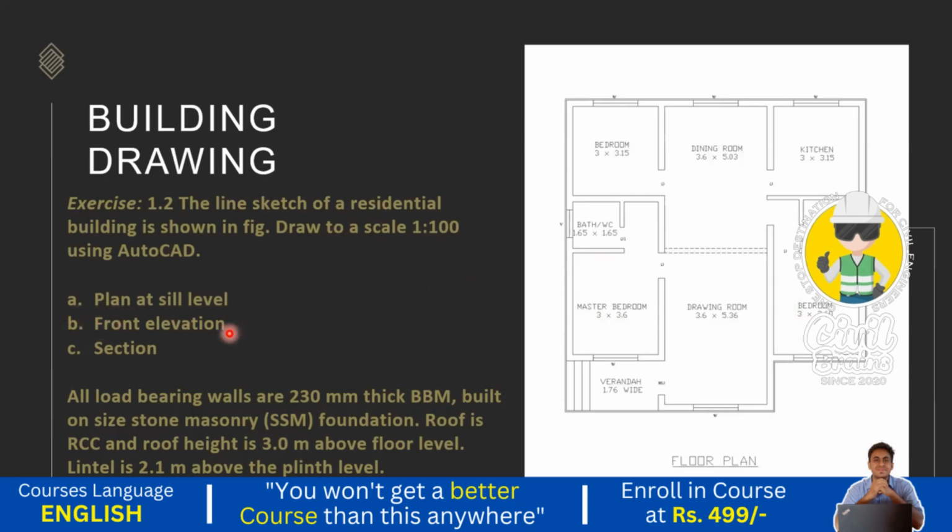So what we need to draw is the plan at sill level, front elevation, and section. So what is given here? All load bearing walls. Everything is a load bearing wall of thickness 230 mm in BBM. Whatever walls you can see here, everything is built of 230 mm.